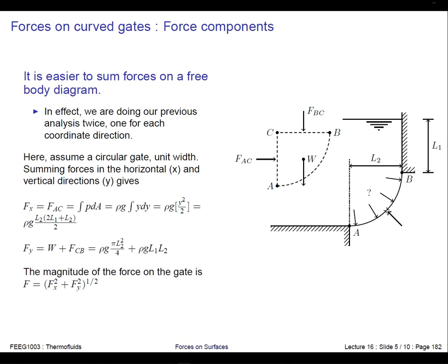So let's work out the force in the X direction first of all. So that's FAC, and if we wanted to work out an elemental force, that would be PdA, and then we're going to integrate in the Y direction, vertical direction, and we're going to end up working out the net force. So we've got the integral of PdA, so P is rho g Y, and dA is just dY because it's unit width. So dA is effectively W dY, but we're going to assume W is 1, it's unit width.